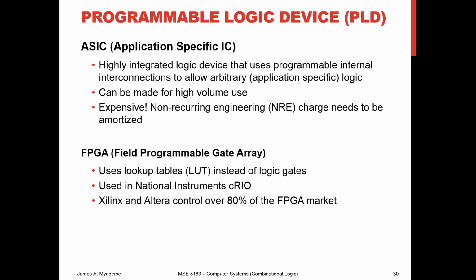An FPGA, instead of using logic gates, is going to use lookup tables. And we have some examples. So if you take the next class in this sequence, 6183, we'll use the National Instruments cRIO, or now the myRIO platform, which contains FPGAs. It's a different way of implementing, but it's the same sort of idea that you're going to set the ones that you need, and the rest of them that you don't need are going to be wasted for that application. But it is reprogrammable, and it's very quickly reprogrammable, which is great.